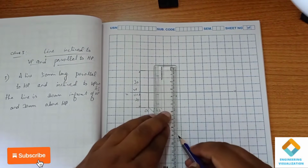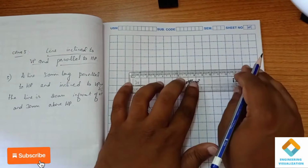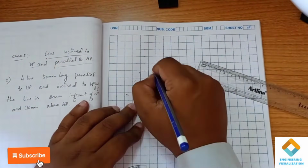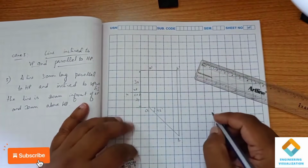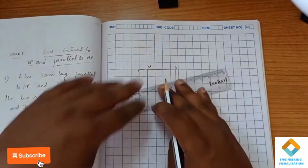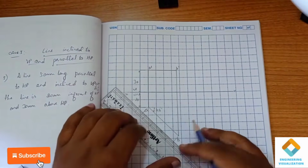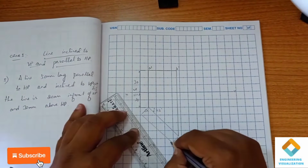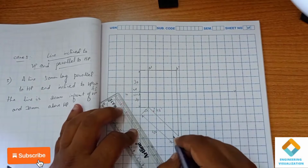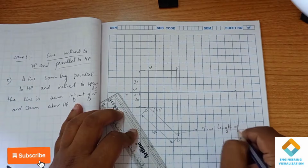Now projecting upward, here we get the front view. So this is B dash, B dash. Okay, so this completes the problem. You can see this is the true length of line. So it is 50, right? If the length of line remains the same after projection, we call that the true length of line.